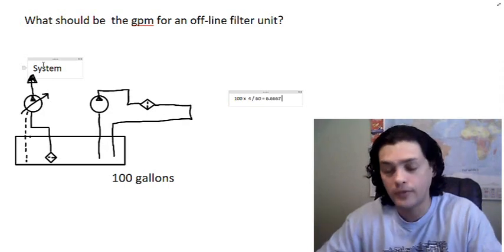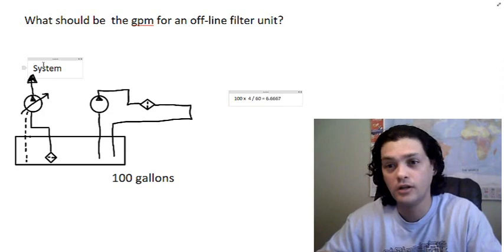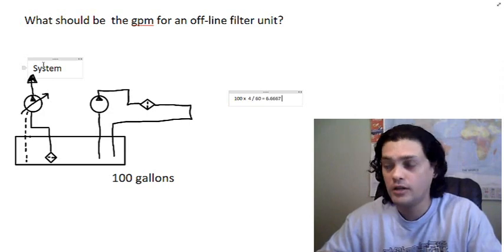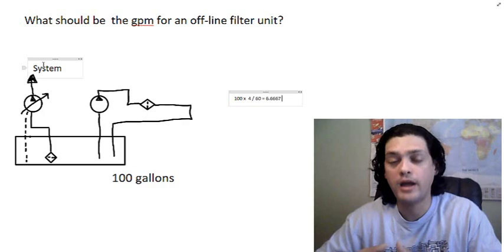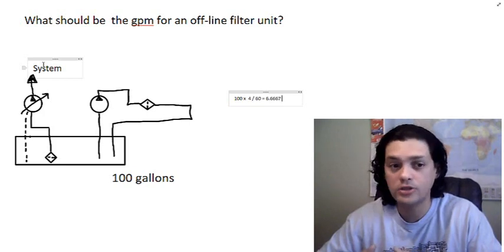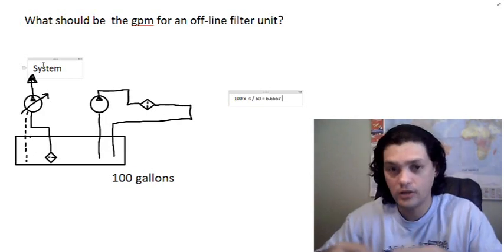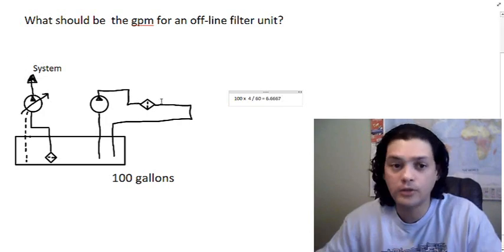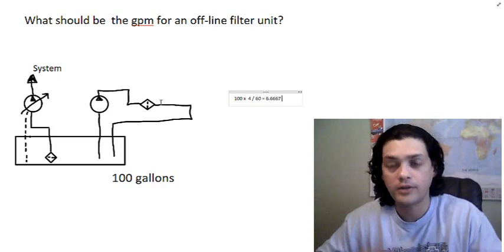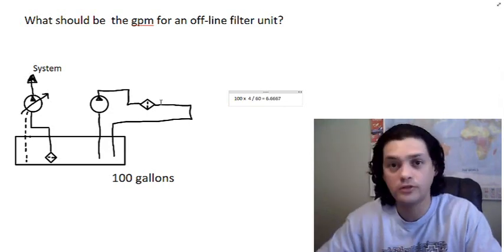So let's say you have a pressure filter that's at 10 micron, and then you put the same filter at 5 micron, let's say. It generates back pressure in the main line. So now the system is operating with more pressure, and also the filter is going to get dirtier faster because the pressure differential indicator is already going up. The same thing happens with the offline filtering unit. You have a pressure indicator that, if you put a 20 micron versus a 5 micron, sure enough it may get dirtier faster just because of the pressure differential, how it works.